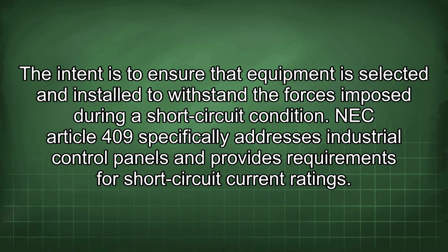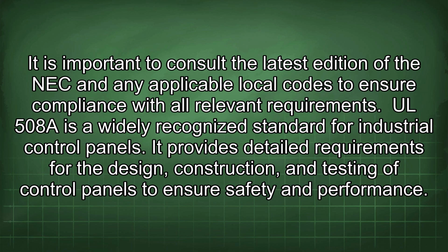NEC Article 409 specifically addresses industrial control panels and provides requirements for short-circuit current ratings. It is important to consult the latest edition of the NEC and any applicable local codes to ensure compliance with all relevant requirements. UL 508 is a widely recognized standard for industrial control panels. It provides detailed requirements for the design, construction, and testing of control panels to ensure safety and performance.